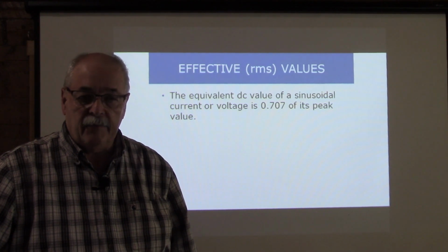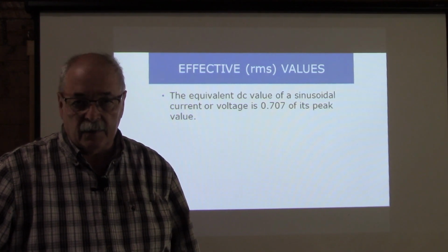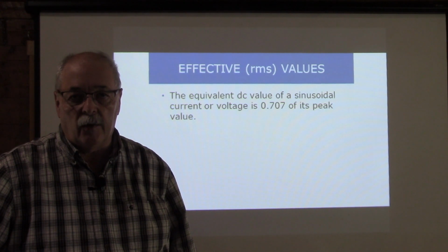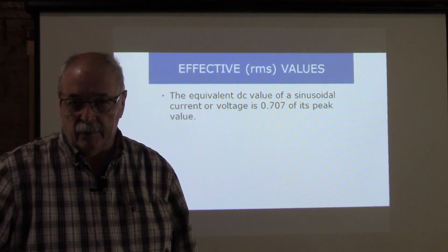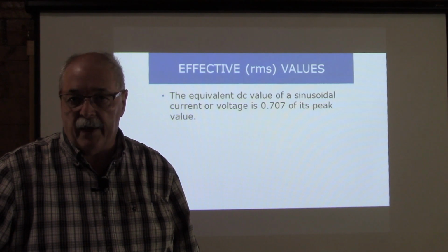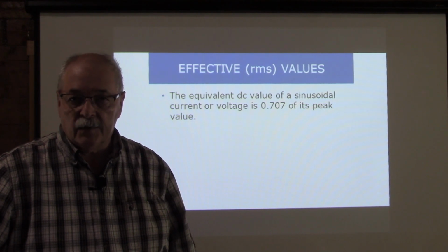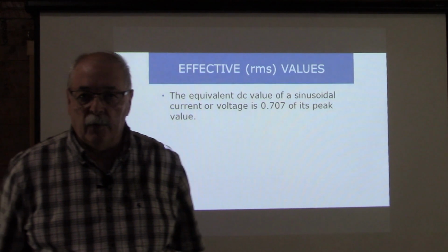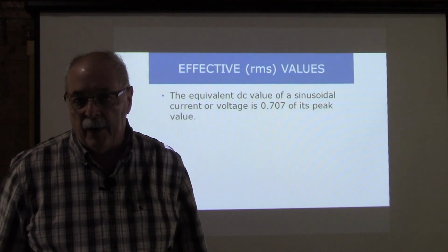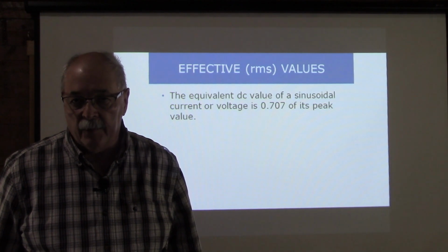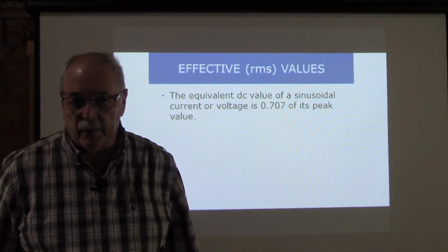And if you're buying a stereo system, some kind of a sound system for your home, the ratings for the audio output on it can be written either as peak values or RMS values. So if you sell it with peak values, it sounds like a lot more output than the RMS value. But you have to understand the relationship between those two.